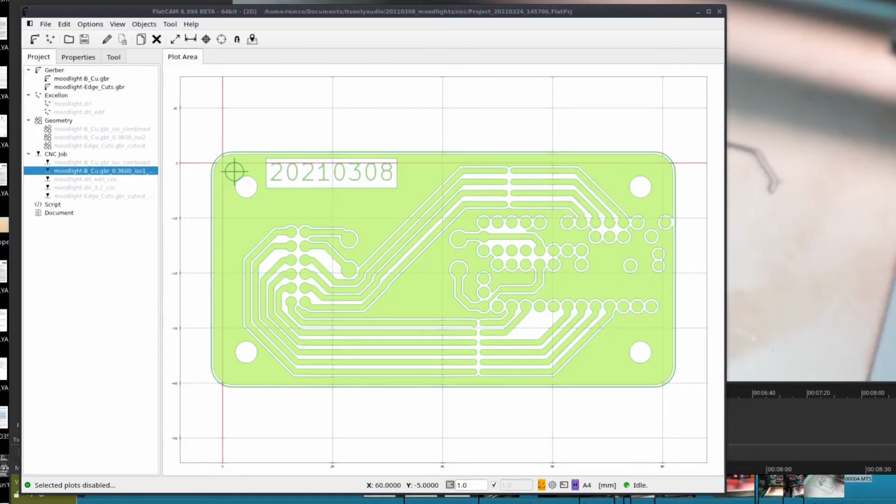So here you see I've redesigned the board a little bit. First of all, I've made the traces wider. But I also put the traces closer together, because when you start to learn about CNC, you figure that you want to actually cut as small as possible. So putting these traces further apart is not going to do you any good. You won't get any extra isolation because you want to run a low number of isolation routes, and you will just end up with a giant copper island between your tracks. So I put them closer together. Here they are a little bit further apart.